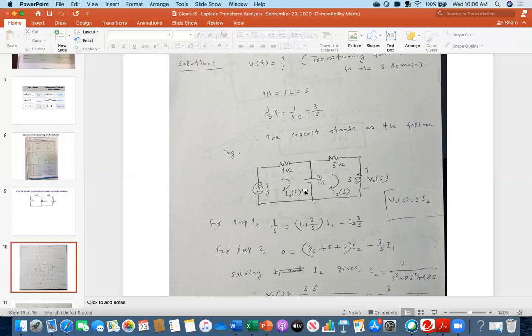So you see the expression, there is no j. There is no angle. Because there is no j and no angle, you don't need to apply the phasor technique. You can fully forget the phasor technique. This circuit is simple algebra, there is no angle, nothing. Just numbers: 1 over s, 3 over s, s, these numbers.